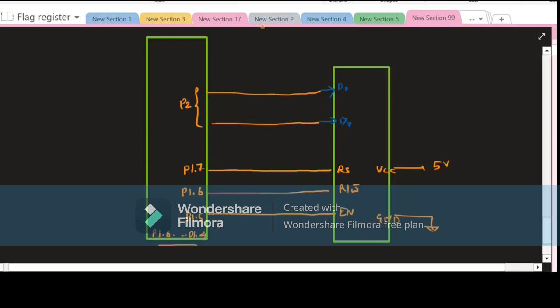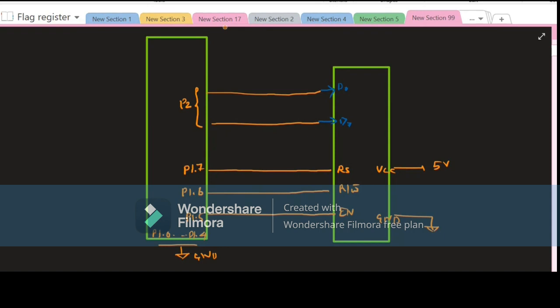as a ground. It basically depends upon you which port bit you want to use. That's it. So this is what you are selecting, and this is the picture of your connection. That means you are connecting this one with this one, this one, this one, and VCC. So this is 1, this is 2, 3, 4, and 5 and 6. This is the 6 pins, 7 pins we basically require to interface our microcontroller with our LCD.